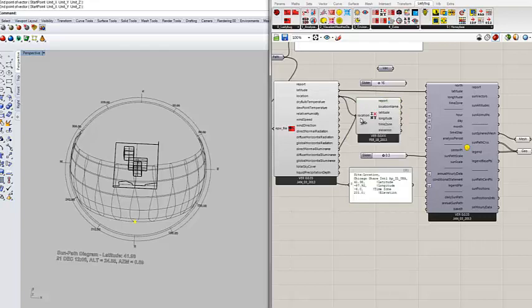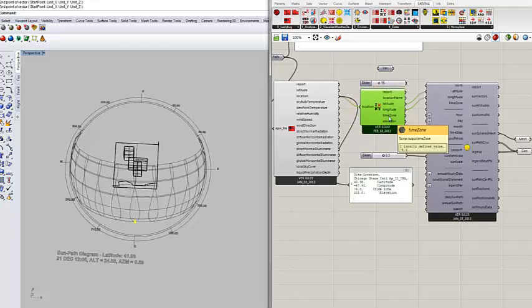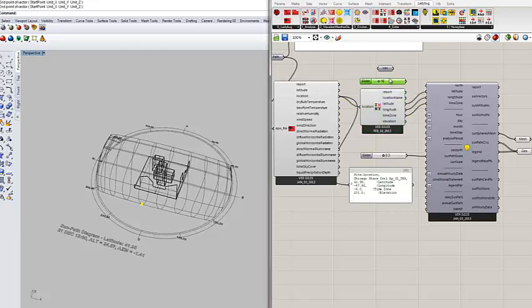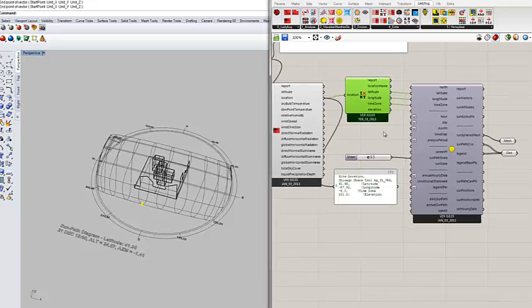And you can connect the location, and it basically explodes the location for you. So it exploded, and it decomposed this string into different outputs. So I can use the latitude from here, the longitude, and now I'm connecting the time zone. So just look at what's happening here. It will move the sun a little bit, right? So this is all the difference. In many cases it really doesn't matter, but if you want it to be more accurate, this is the way that I'm showing.